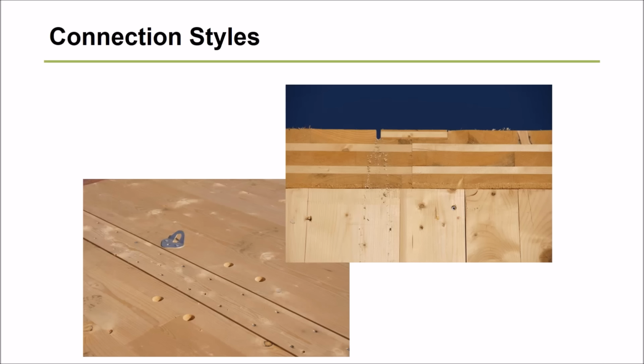So what might that look like in the field? This is a picture, I think, of that school that Michelle mentioned, the first school in the U.S. to use CLT. Here we see the two different panels with the spline resting between them, and in this case, I believe they're nails stitching those together along the length of that panel-to-panel connection at the floor system.